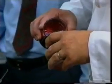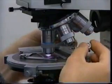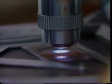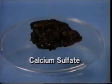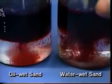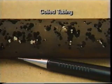Once the decision to acidize has been made, the type of treatment, acid, and chemical additives for the job must be chosen. The treatment procedure must then be carefully evaluated. The complex chemistry of the acid reaction and its byproducts can be very damaging to the formation. Damage can be caused by precipitates, emulsions, changes in formation wetting agents, clay swelling or migration, and the reaction of the acid to downhole equipment, such as tubing, packers, and casing.